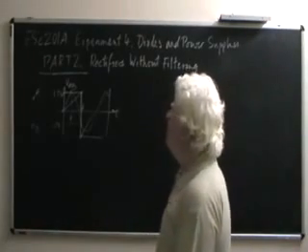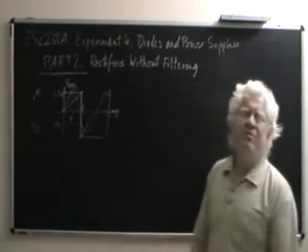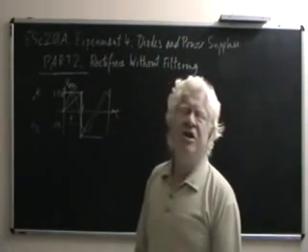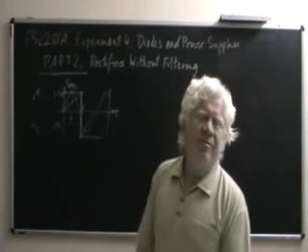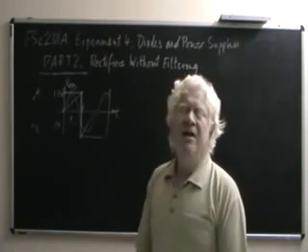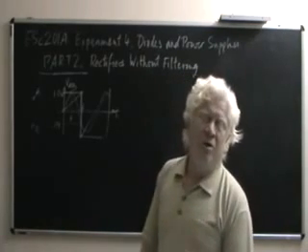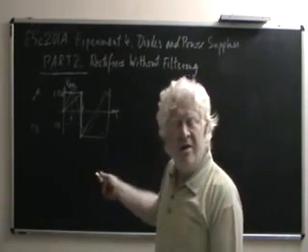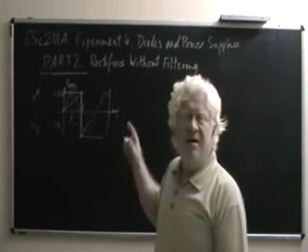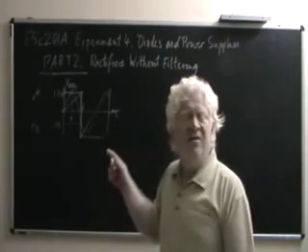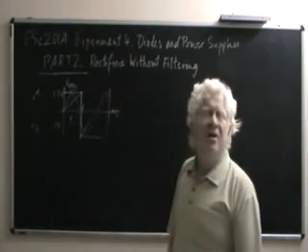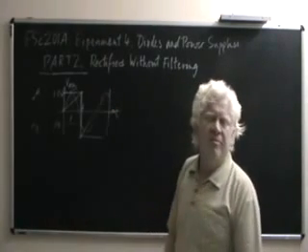Right. So what we want to do with a rectifier is to convert this alternating voltage into a unidirectional voltage. Ideally a constant unidirectional voltage, but at least a unidirectional voltage. The first step we take, that is just a rectifier without additional circuits, will convert a bidirectional or alternating signal into a unidirectional signal.